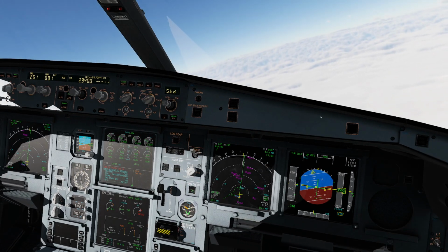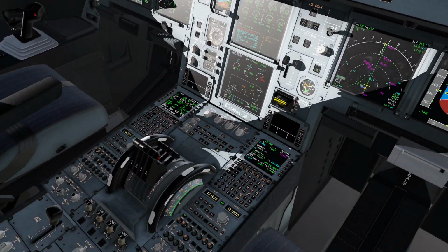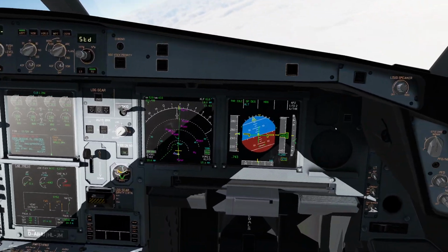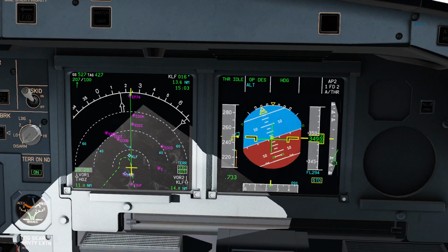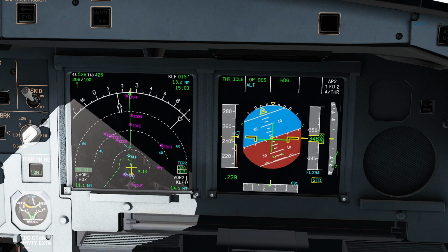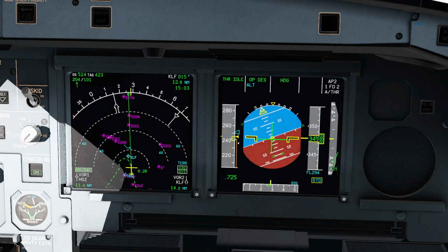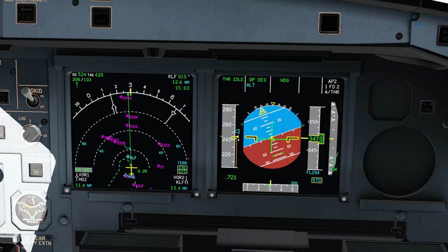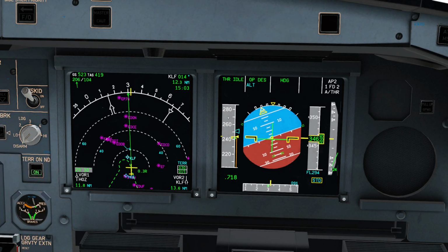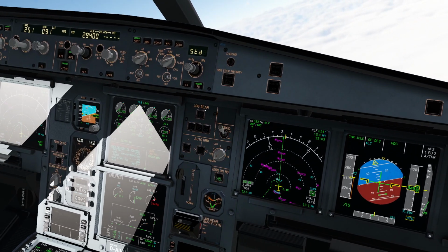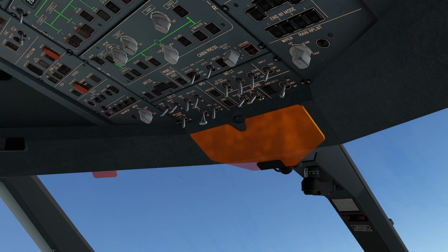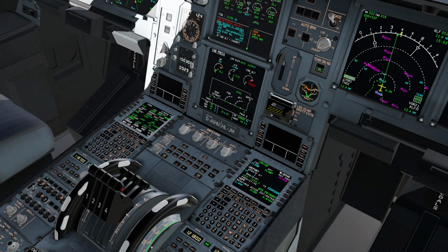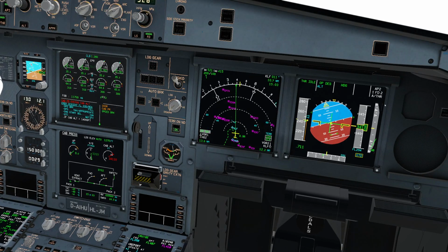Okay, thrust idle, open descent, heading. Now let's get the speed brake out, slowly. You can see how the VLS immediately comes closer. We just need to be careful not to actually enter it. Okay, so pilot monitoring items, masks on, signs on, and FMA check. Okay.